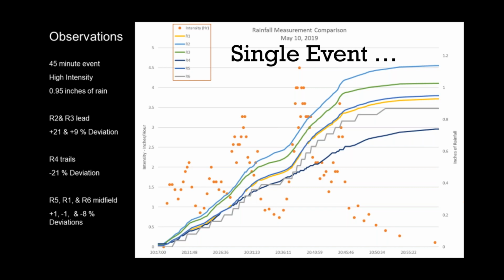So things can change in accuracy, as I said earlier, based on the intensity of the rainfall that's happening. There can be other factors that change that accuracy, but that's one of the biggies if everything else was alike. And here we see plus or minus 20% deviations or errors, all of which is outside the stated range of accuracy from the manufacturer.